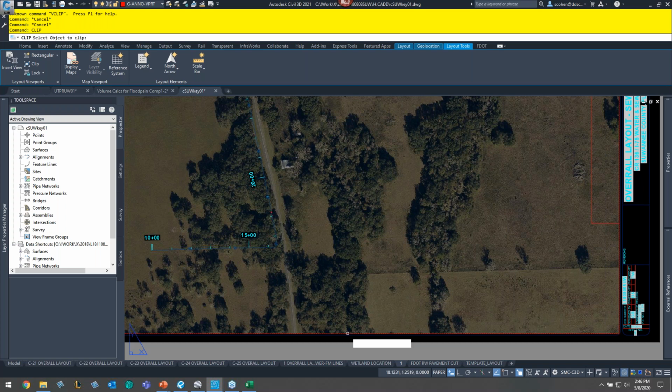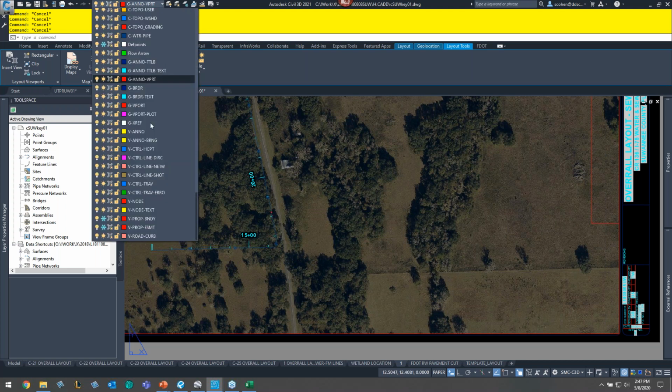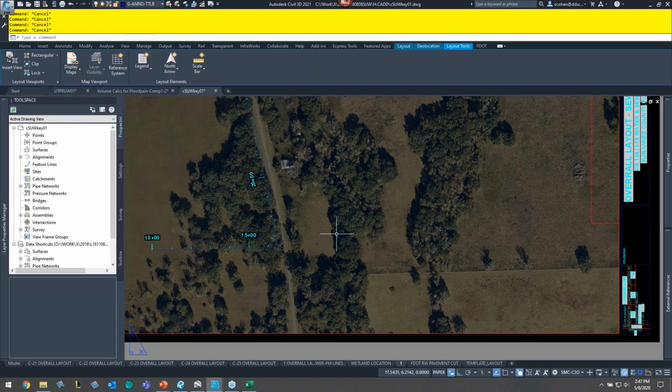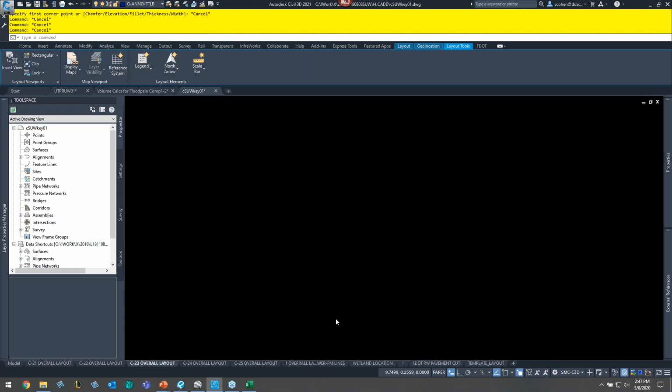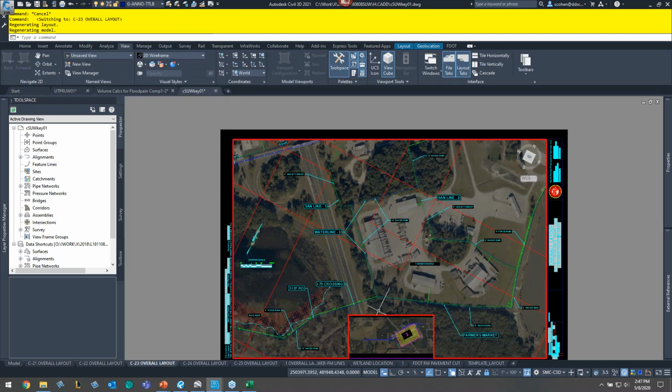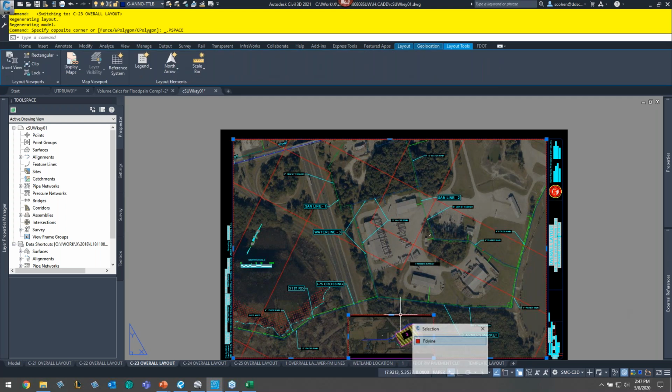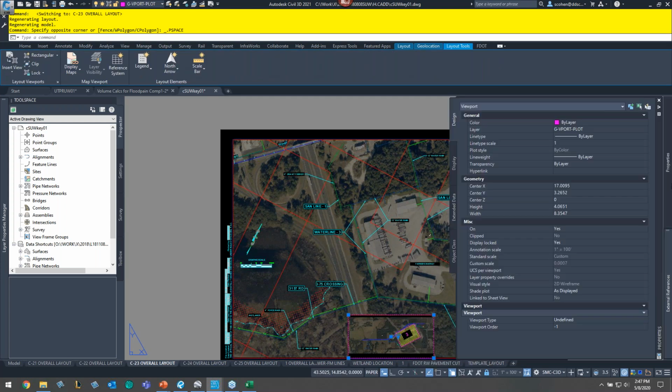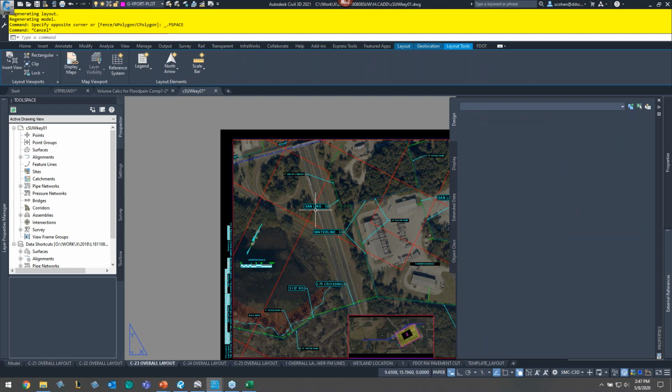And then, when you don't know what to do, as I always say, look to the command line window. Select clipping object or polygonal. I'm going to create a polygon. Actually, let me back up. I forgot. I need to know my shape that I wanted. This I do want to be on a layer because I want it to actually plot. I want a rectangle, and I think I want it to be 8 by, actually, you know what? I'm not going to guess here. Let me just grab the shape here real quickly and see what size it is. What I figured out was the good size. 8 by 4. Yeah, that's what I wanted.